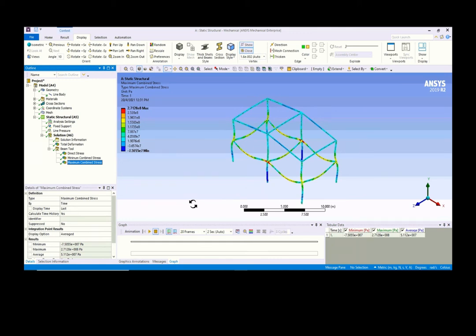So that is an example of dealing with frames. This is a simple frame, but it can go further. You can model it with these line bodies. It can be very simple, and in fact you can even model an entire oil and gas platform with these techniques. It is simple and fast in terms of solving, instead of drawing the whole 3D CAD model. That is the power of these simplified one-dimensional line elements, line bodies.